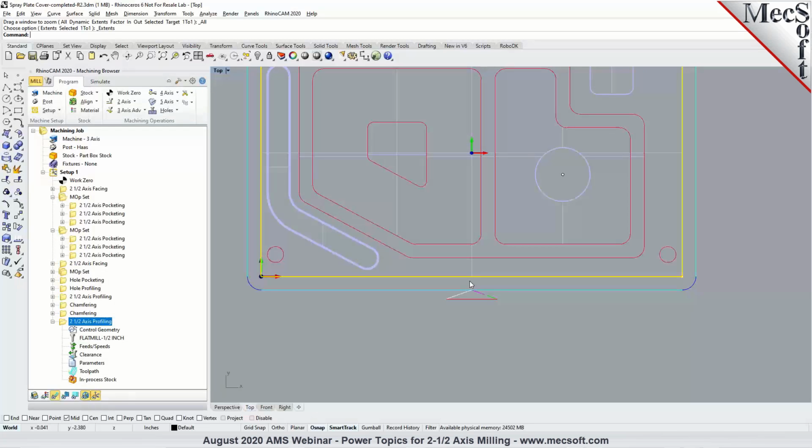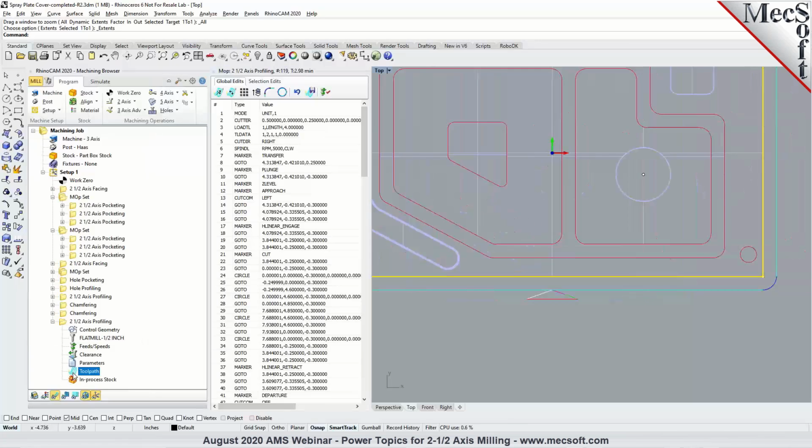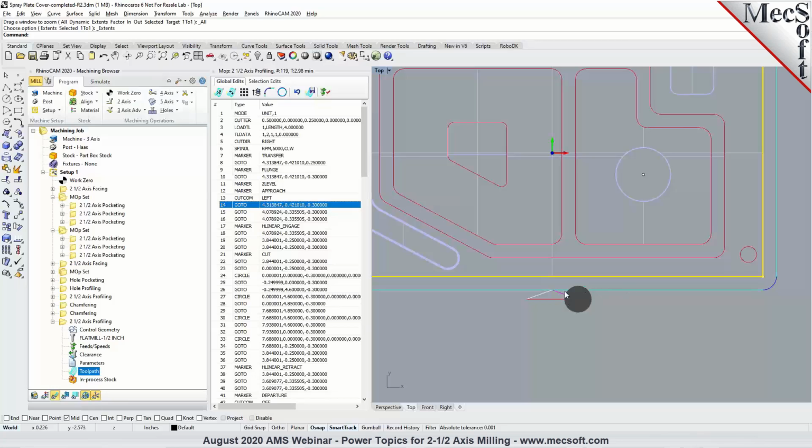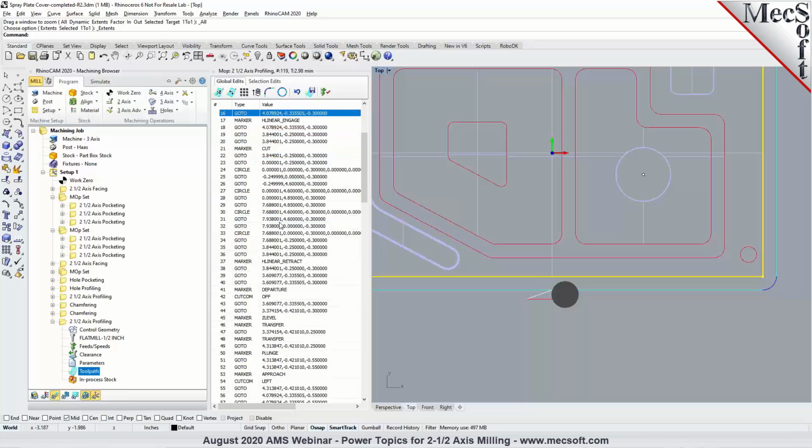And one of the ways you can verify even before you post process the code is you can go into your toolpath editor or toolpath viewer, and you will notice that right after approach motion, you'll see the cut comp left, which is enabling the cutter compensation in here. And I'll toggle off the display of the tool holder, so you can see that the toolpath is still there with the tool geometry. In addition to it, it's outputting the cutter compensation. And right after the departure move, the cutter compensation is being turned off.